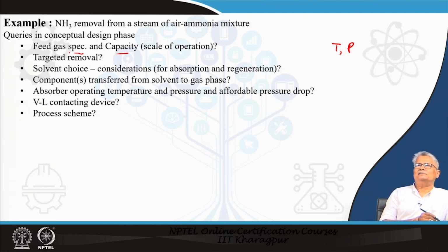Next, perhaps comes the question of the solvent. We need to choose the solvent first. Now, the question is, the simplest thing that we can use here is water, because we all know ammonia is highly soluble in water. Now, the question is not only that solvent choice is important while absorption, it should be easy to regenerate also.